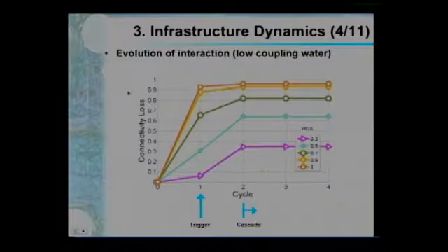This is the connectivity loss in the vertical axis of the water system. At time 0, nothing has happened. At time 1, the earthquake occurs. And we have earthquakes of different intensities from 0.3 to 1. This scale of PGA is a standard metric for measuring the intensity of earthquakes. It's the peak ground acceleration, a percentage of the acceleration of gravity. So we have the event. This is failure of the components due to the direct exposure to the earthquake.